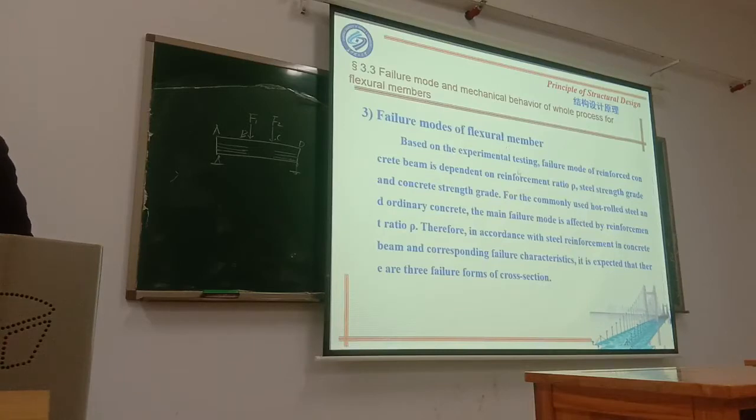So based on the experimental testing, the failure mode of the reinforced concrete beam is dependent on the reinforcement ratio, steel strength grade and concrete strength grade. For the commonly used hot rolled steel and ordinary concrete, the main failure mode is affected by the reinforcement ratio.